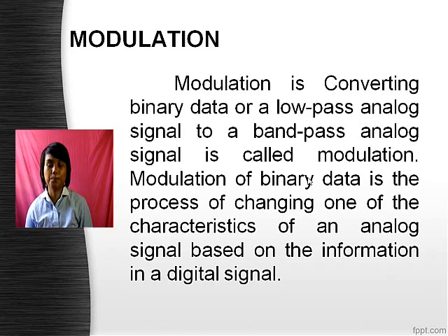Modulation for what reason? First, information such as sound is represented by the modulation of the signal. A signal is modulated when one of its parameters changes with time. I will discuss both amplitude and frequency modulation below. Another reason to modulate a signal is interference. Once I start sending a signal of about 500 Hz, any other 500 Hz signal would interfere with it, so I could only broadcast one signal of addressable range frequencies in any region at a time.